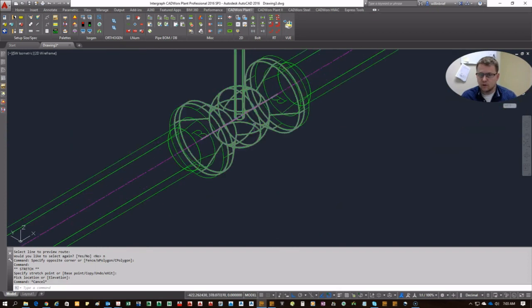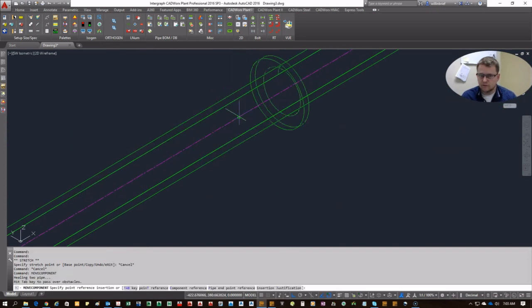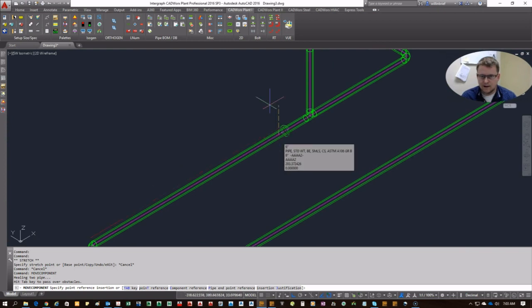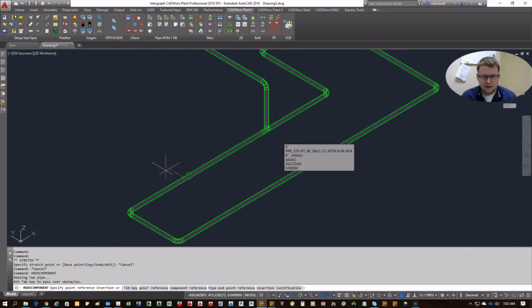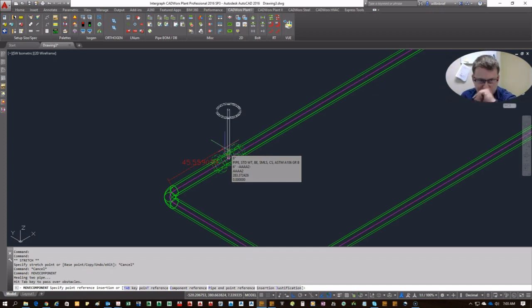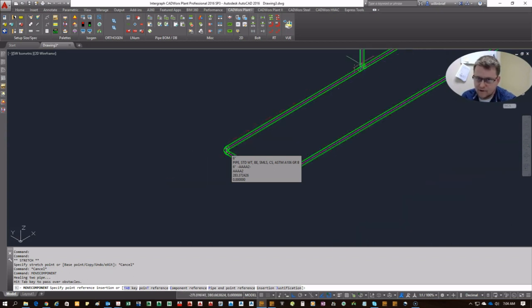After you've generated a component, you can click on the center point there, the little grip, and you now have the capacity to move it. As you can see, as I'm moving this, although not perfectly, it generates a little dimension from the end of pipe, and you can tweak your settings to allow you to see that from various options.